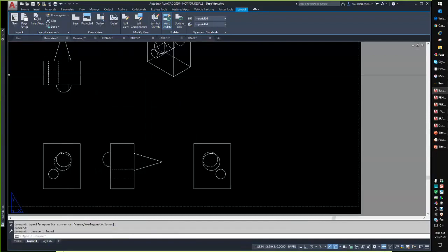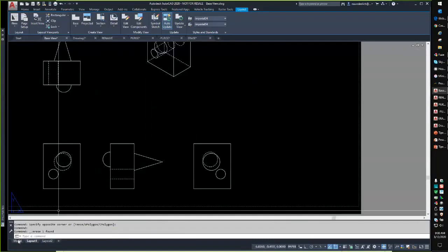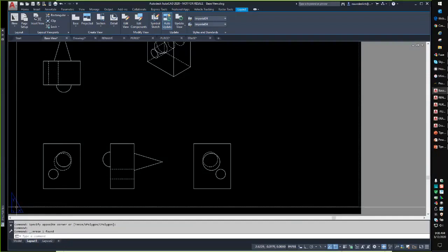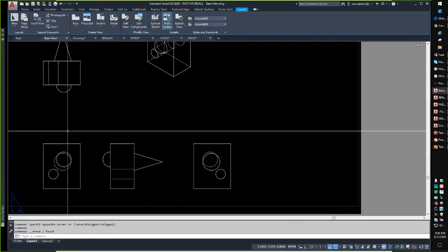Where would I look for a layout tab if working in Civil 3D? First thing you have to do is down here at the bottom should be your layouts. Now, I will warn you, one of the things about Civil 3D is you're only going to see objects that are truly three-dimensional, such as surfaces. Your alignments will not come in a base view. You will only see surfaces, corridors, things like that. Anything that's 3D, because most of your alignments are 2D, and you will not see that.